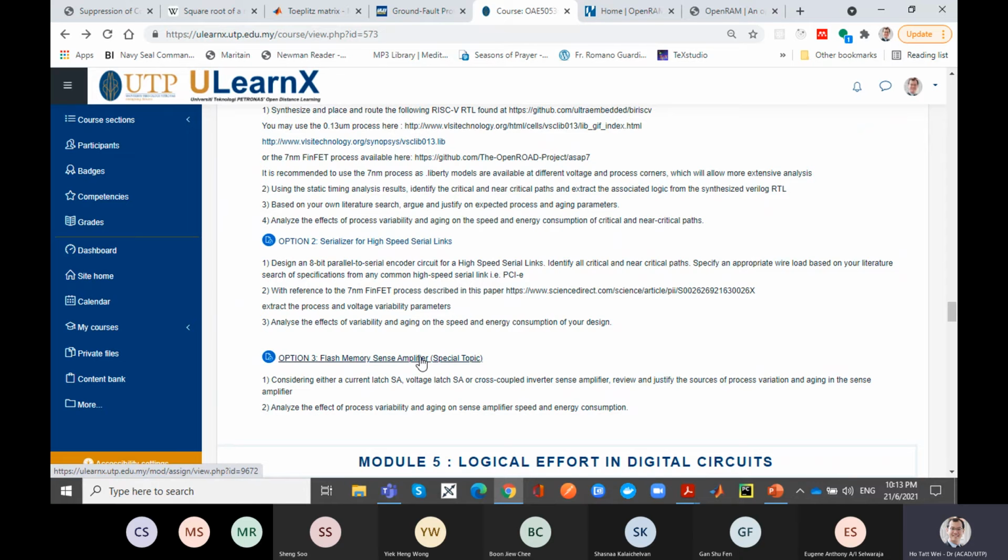There could be certain logical implementations that are intrinsically faster than others, or intrinsically save more energy than others. You won't do this for the whole chip, but let's say you have a few outstanding ones, really the critical part or near critical part, boom, all the way at one end. These are the ones that you might go in and hand tune a little bit.